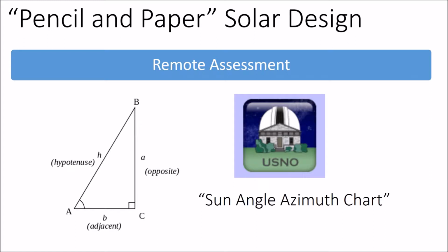But we also talked about in the intro to solar program that there's now a variety of system designs that you can do to mitigate shade, whether it's a string inverter with multiple power point tracking. It used to be the inverters only had one power point tracking. So if you had 5 or 6 circuits on the solar array, you would combine them into one circuit before landing on the inverter, and the inverter would just track the power point of the system.